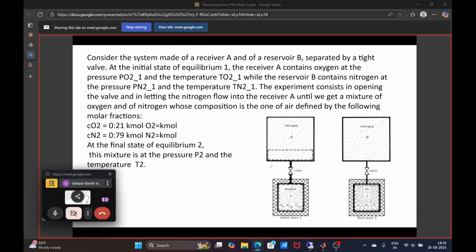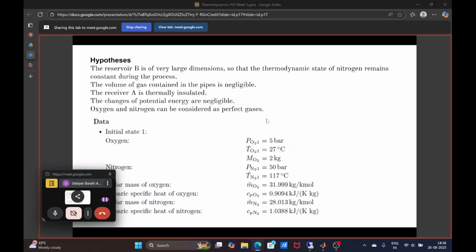So in this case, this is like the previous problem where we did two gases getting mixed. It turns out to be the same kind of problem. This is the nitrogen which will be entering the oxygen tank, so that portion is again considered to be in the control volume. So it's not just the tank but also the mass of nitrogen which is entering the tank. That is the control volume which we are taking.